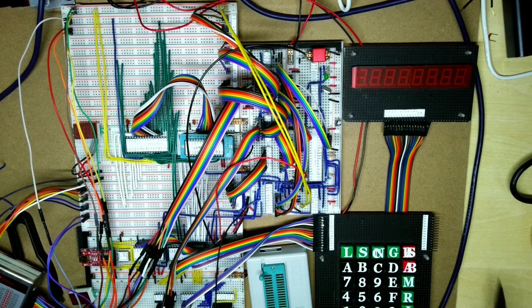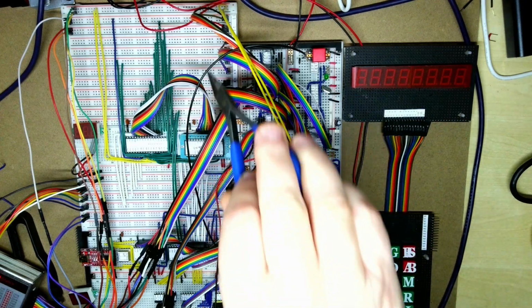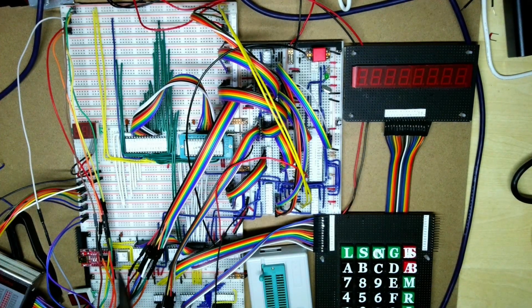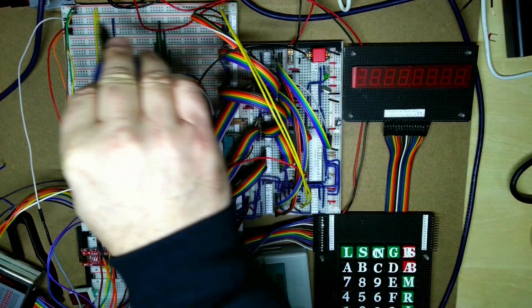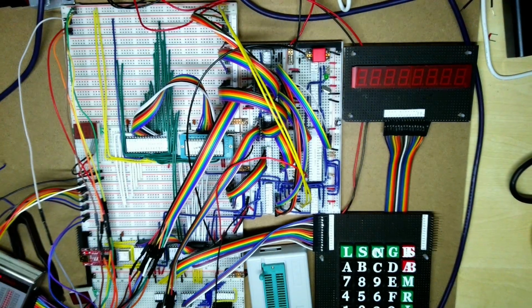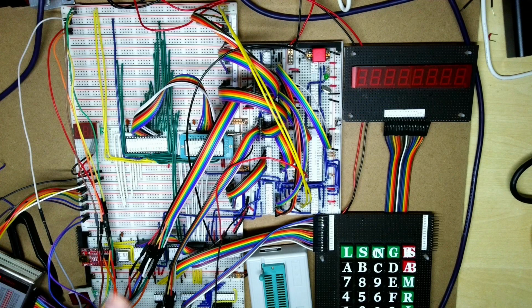Okay, so I've updated the monitor and the PLD. We've installed all of the IO and the memory read, memory write. So the IO is now down here and the memory read, memory write's up here. You'll notice I've got some of the logic analyzer plugged into the address and data lines. There were one or two minor issues that I had, which I'll explain. I'm going to go through the code.